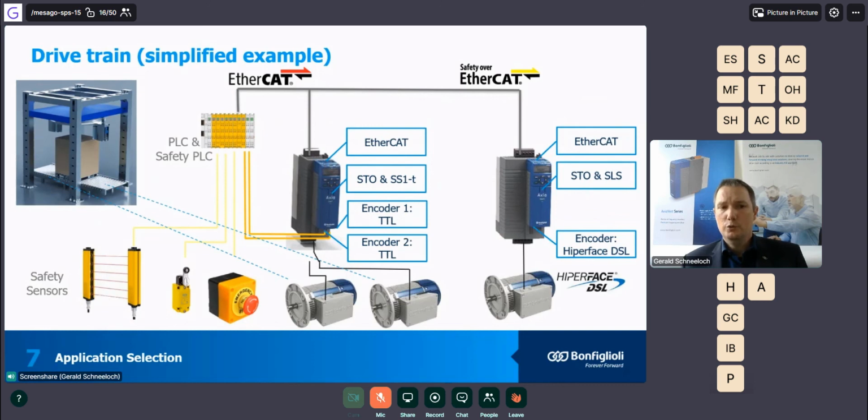In my example, we use EtherCAT as field bus, where a PLC and a safety PLC take care of the machine operation. Failsafe over EtherCAT and the usage of a black channel for functional safety commands can be easily used for the drive which have higher requirements from a functional safety point of view, like the rotation ring unit.